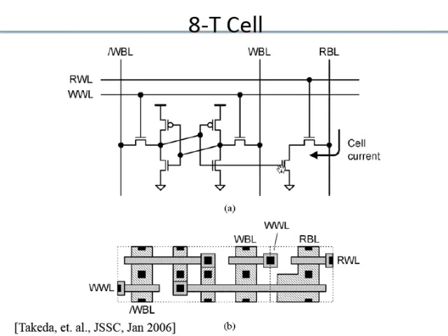So what is happening is that this transistor's gate is coming from the internal node of the cell. And this is the access device. Now there is another word line for the read, called the read word line, and then you have the read bit line. So now what you do, you precharge the bit line, which is just the read bit line, and then when I want to read a cell, I turn on the read word line. So this transistor turns on.